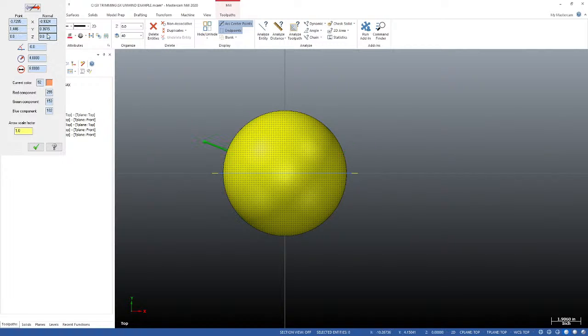And keep in mind, this normal vector is a 3D length line where the start point is the back end of this arrow and the end point is the tip of the vector. So it doesn't start from the origin. It doesn't start from XYZ 0, which is why these numbers basically always add up to a 3D length of 1.